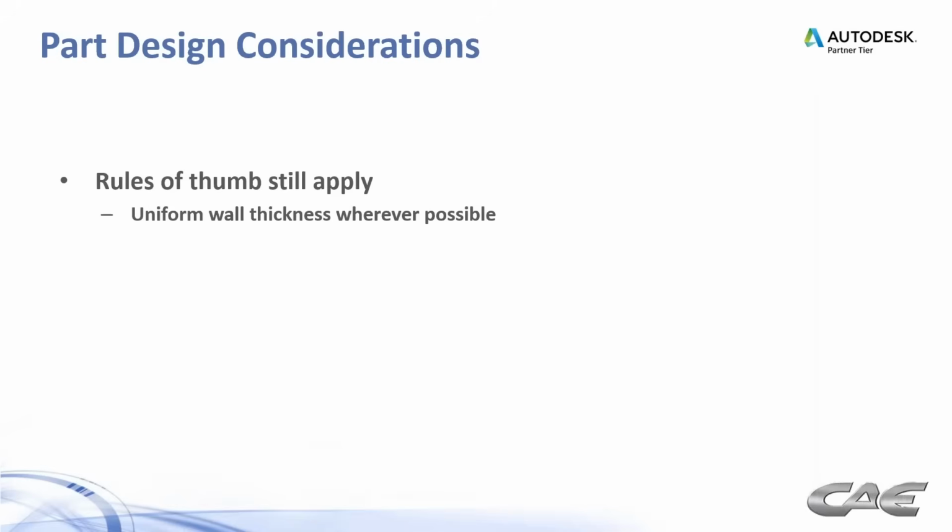So just to wrap that piece of it up, those are different ways to model things in Moldflow, and the takeaway from the 2-shot overmolding with cooling is that it's a difficult thing to do in Moldflow at this point. It can be done, and we're at a point right now where we really want to move forward with this and get a lot more feedback and data to see what really is the best approach on that.